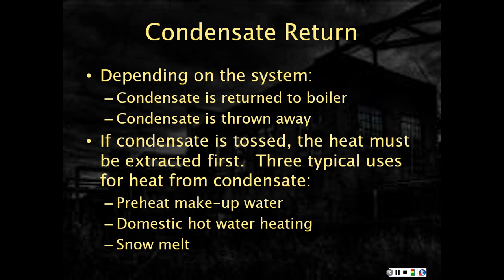Now, the reason here in Michigan, or at least in Grand Rapids, Michigan, the condensate is thrown away is the source of the steam is so far away. Somebody's decided that it was a lot cheaper just to have everybody using the steam pitch the condensate and use constant makeup water in the boiler. So again, it's the boiler used for the district steam in Grand Rapids, Michigan. The waste heat boiler is so far away that they're not returning the condensate. And again, the heat has to be dissipated out of the condensate prior to pitching.